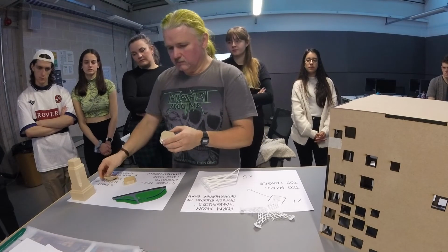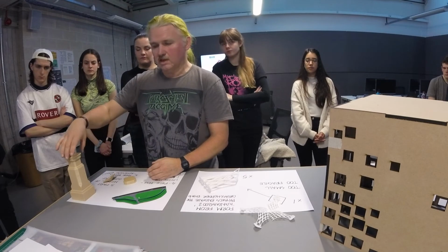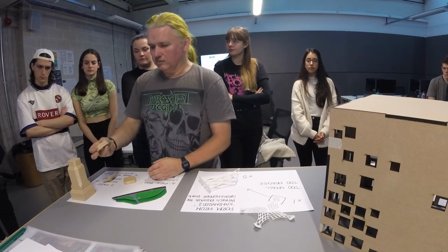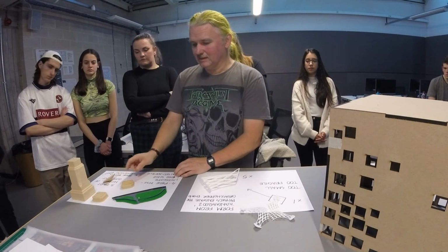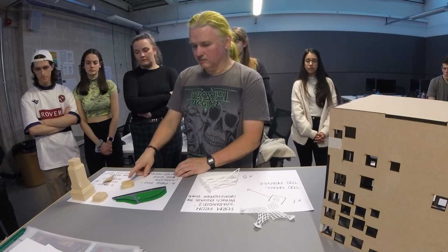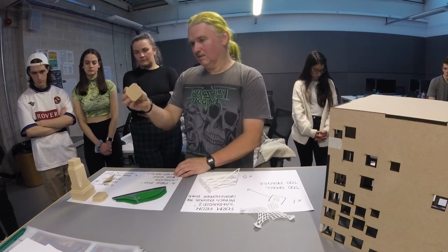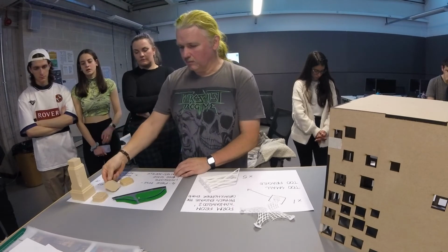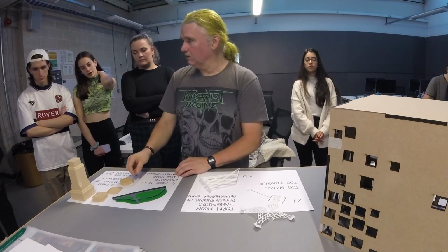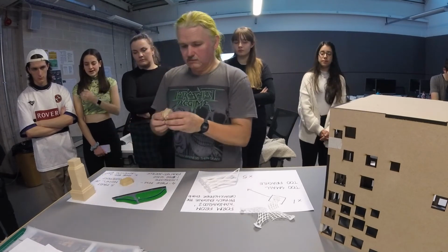Blue tack's pretty good. This bit, because of the overhang, and I didn't want any kind of scraping, I printed the other way around. Okay, the first attempt at that didn't print very well. It's not very flat. It kind of rocks, and so you can definitely see there's a problem in that one. And then the final bit, this wee pyramid, printed the right way up. So that's the kind of thing you've got to do.